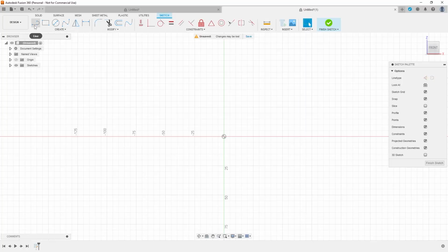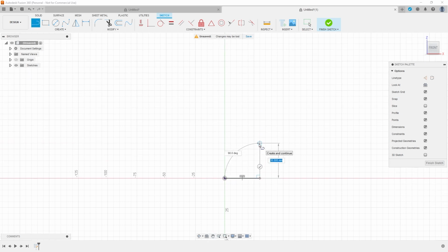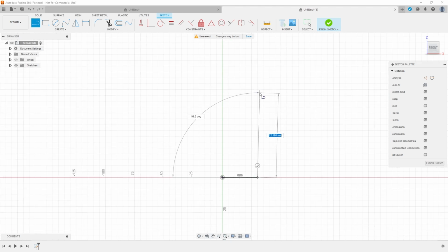So I'm going to use the line tool. I'm going to draw what I think is the bottle profile. We're going to come up a little bit. Let's hold the bottle in my hand. It steps in, steps up, it comes back out for the lid. I'm modeling the lid all as one here. I'm not modeling anything in terms of like a removable cap. We've got like this step effect. Okay, so this looks incredibly strange right now.